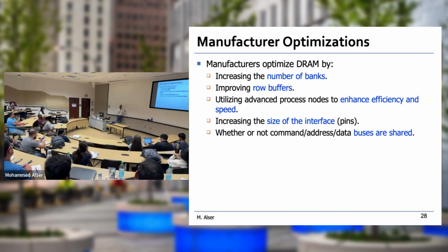Now, if you look into the single DIMM itself, what will happen if it has a really larger capacity, meaning that it fits more data, meaning that you might need the same row again and again. So you activate one row, it's already in the row buffer, and now you're going back to get the same data again. So you will find it most of the time because it's already in the row buffer.